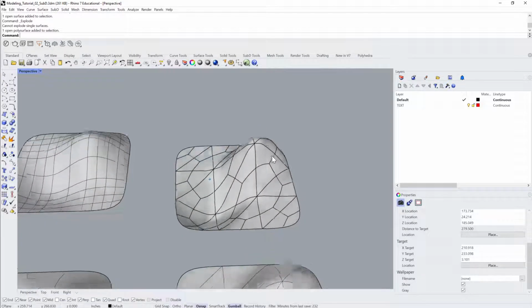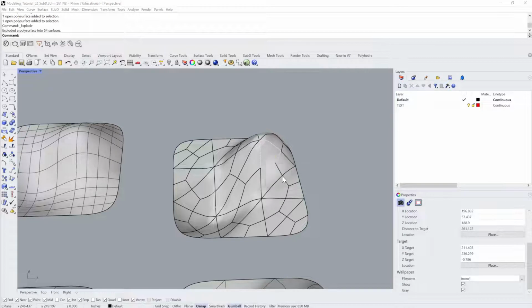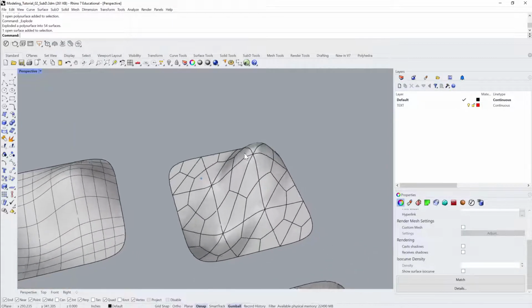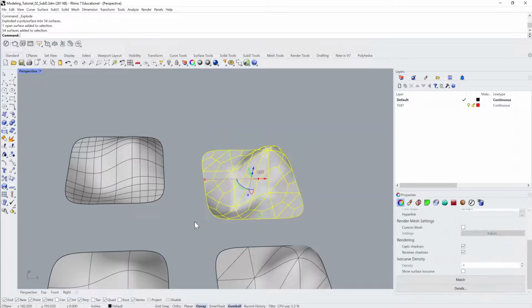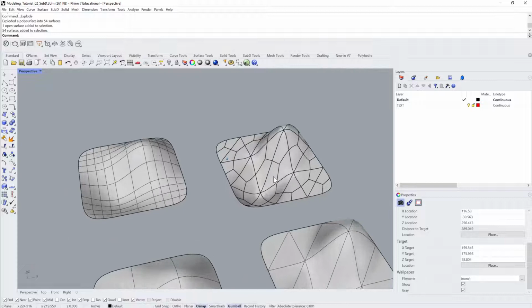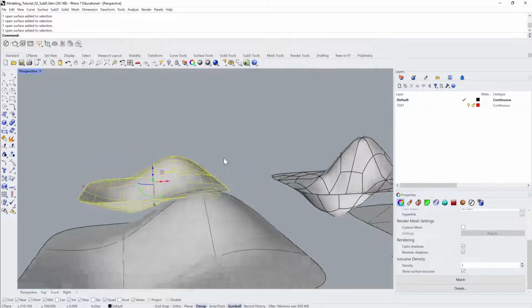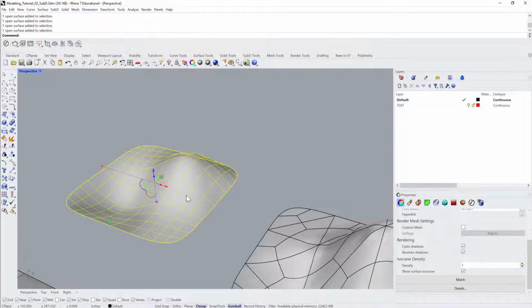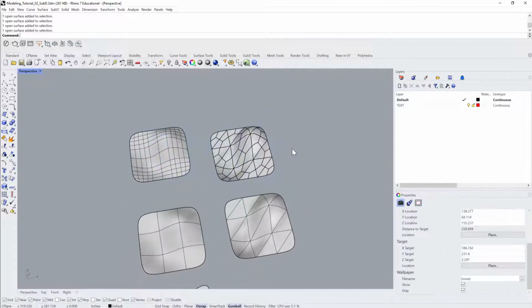I've got all of these different surfaces which are now pieced together. So this is not what we would want if we are looking for curved geometry, simply because we would probably go to NURBS at some point and we wouldn't want all of these surface patches. It would be much cleaner to have as few surfaces as possible. So you want your geometry workflow to look like that.